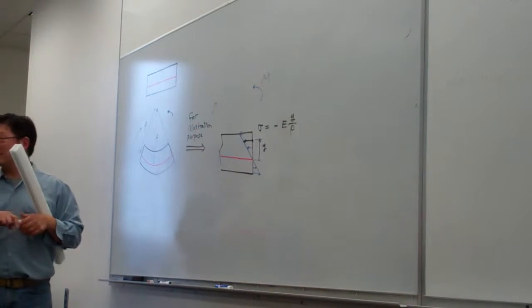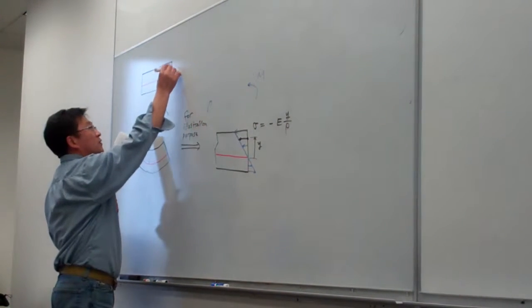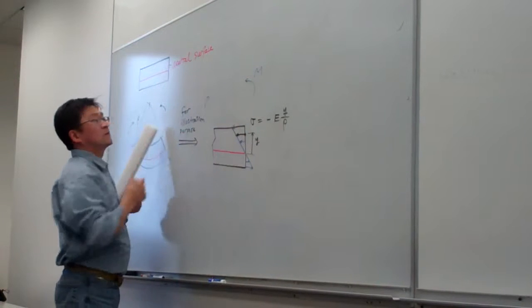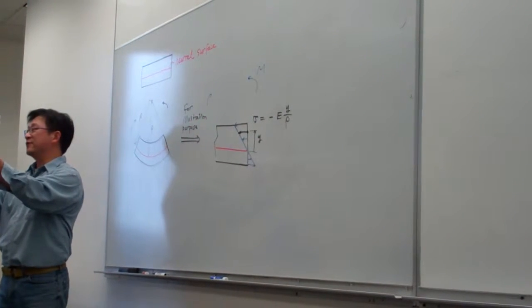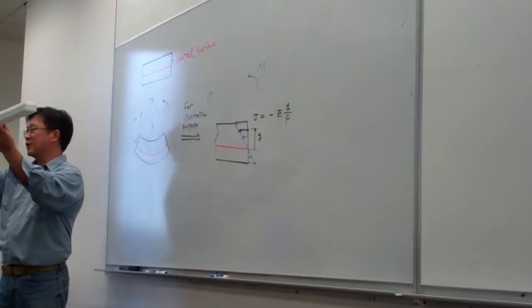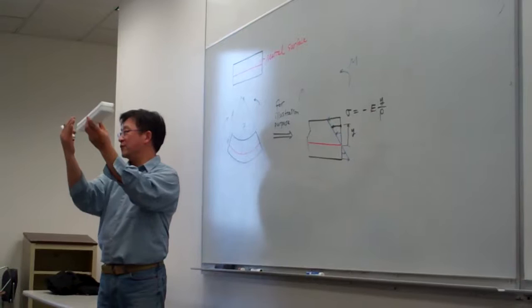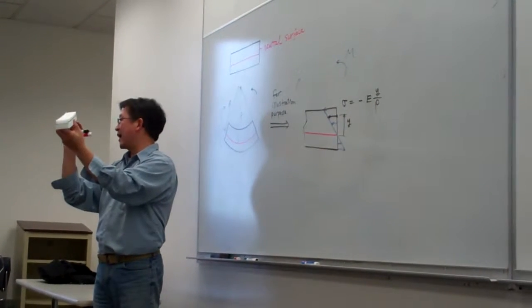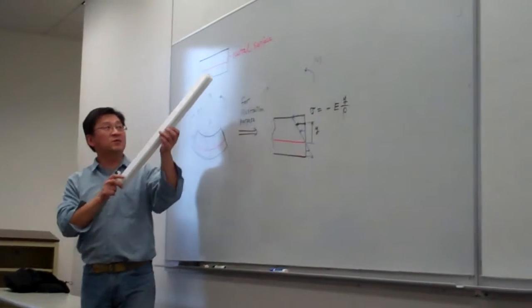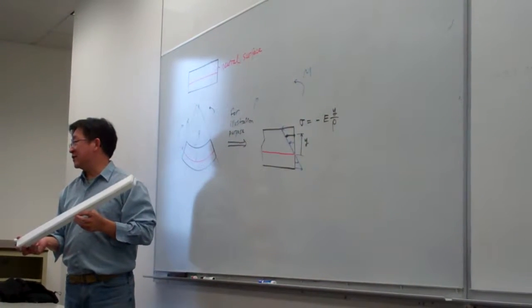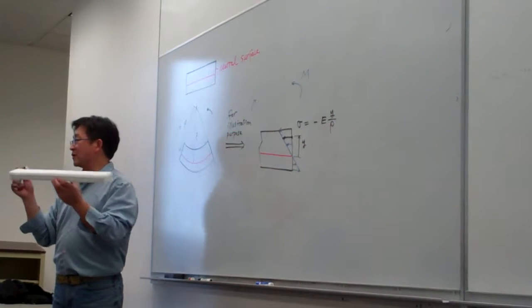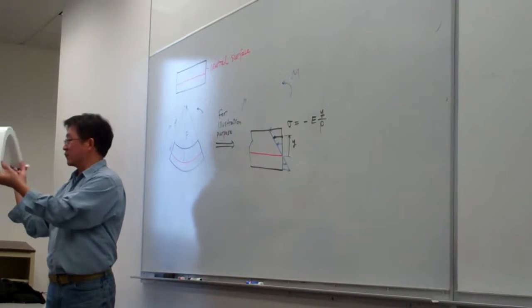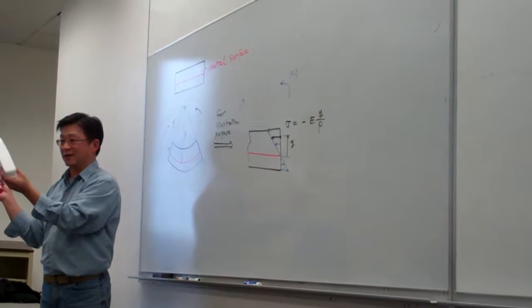In terms of a 3D scenario, we call this a neutral surface. Looking at this in 3D, this line represents the intersection of a specific plane with this side. So the plane constituted by this green line is a plane. In solid mechanics, we say that is a neutral surface. All the parallel fibers on the neutral surface are undeformed due to bending. Doesn't matter which kind of bending you do, the green fiber always remains at its original length.